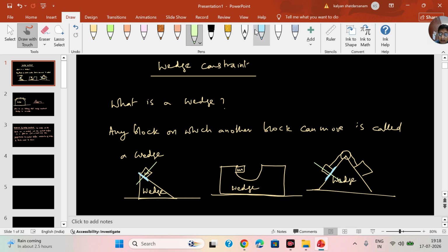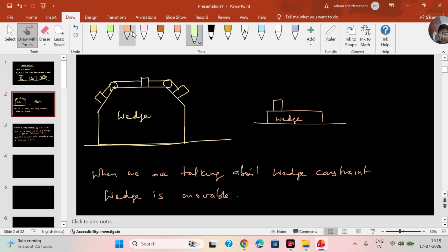Similarly here, this is the contact surface, and perpendicular to contact surface, acceleration of wedge and block must be same if they are to remain in contact. Why like that? What is the reason? It will become more clear if you look at this example. See, this is the contact surface, perpendicular to contact surface means in this direction. The block and wedge should have the same acceleration. If they have different accelerations, then they will lose contact.